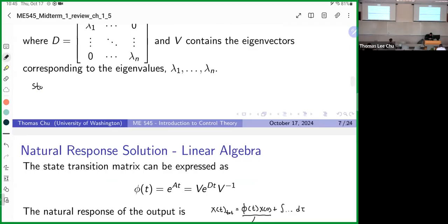A is just a matrix that, so I think maybe when I say state space, I want you to specify A, B, C, and D, and these are your matrices. But when I say state transition matrix, and this is the way it's defined in this class and in 547, actually in all controls classes, this is a standardized definition. Then you think of phi of t, which is equal to e to the At, and you use this A here. So that's how they're related.